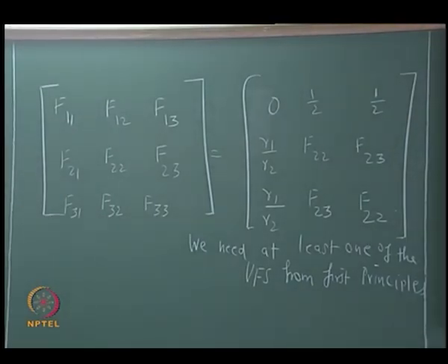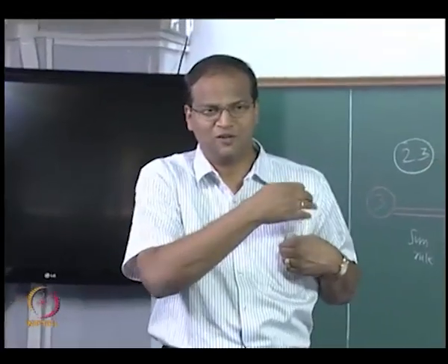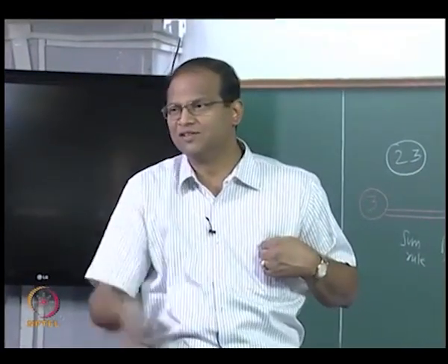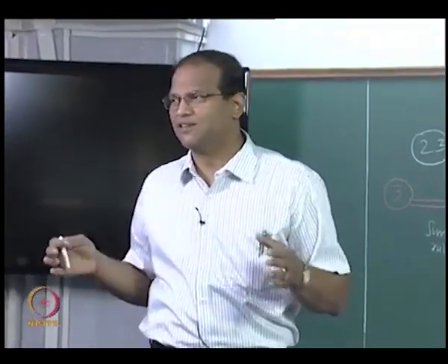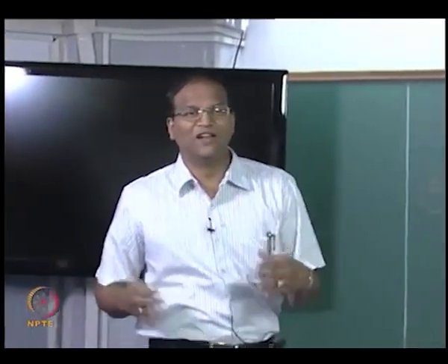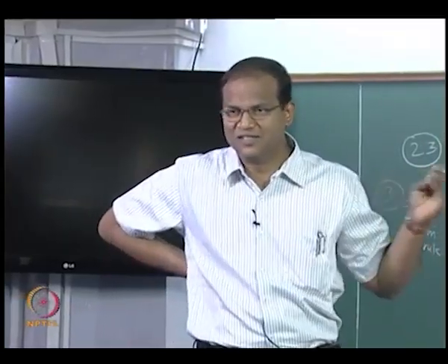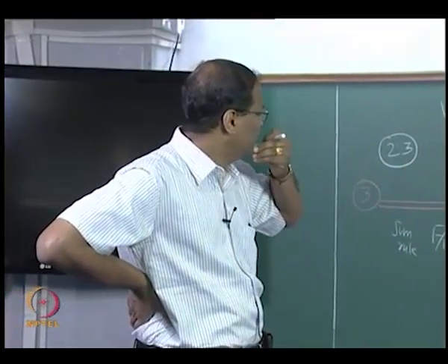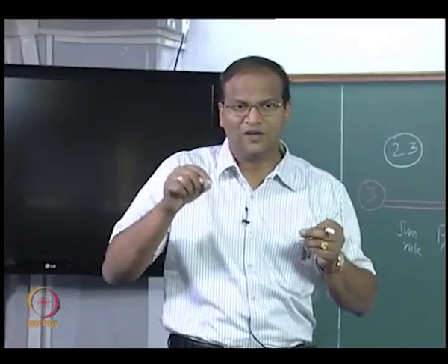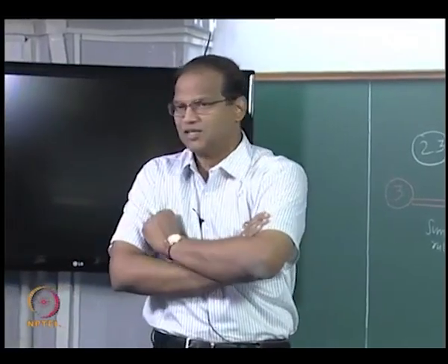I must tell you that I am equally surprised that such a simple problem is not possible for us to solve, because I have not taken it from somewhere. Yesterday on the spot I thought we would work out a simple case, and I am completely surprised that we are not able to solve it using view factor algebra. We cannot underestimate it just because there are only 2 surfaces. There should be some way: you have to take cos theta i, cos theta j, dAi, dAj, and integrate by contour integration, and you can get it.